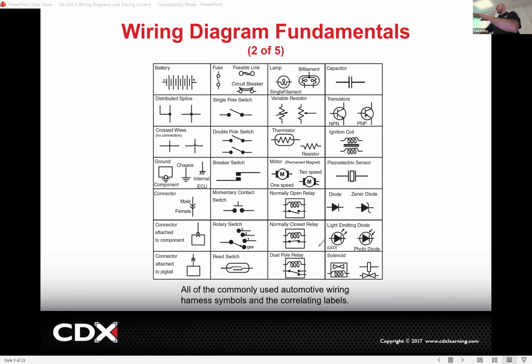Does that make sense? So the wiring diagram, let's see how many speeds we got. We got off, 1, 2, and 3. There's not going to be 4 versions of the wiring diagram. You're going to get one diagram and it's probably going to be drawn in the off position. And then if you know that it's got a problem in speed 2, you're just going to tell yourself, no, it's in speed 2, and then trace it in speed 2, and test it as if you're in speed 2 with the switch in speed 2. Cool. Okay, another type of relay, not a big deal.